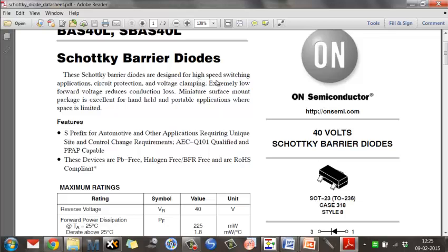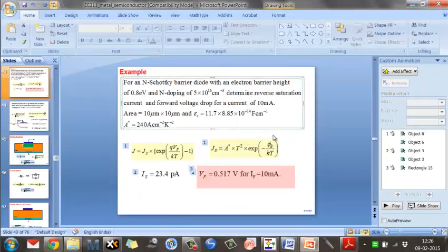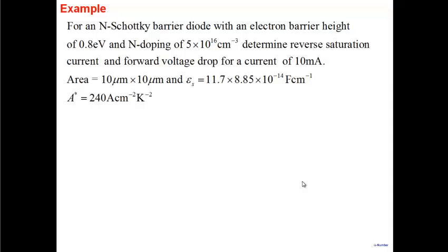These are the two places where Schottky diodes are frequently used. When you have signals which are rapidly varying and want high-speed switching, you use Schottky barrier diodes. And when you require very low voltages, you also use Schottky barrier diodes.